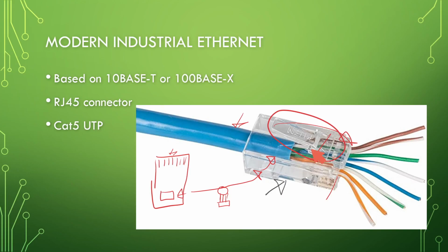The other thing that you guys might remember is when we were doing the cable testing, it was pin 1 good, 2 good, 3 good, 4 good, 5 good, 6 good, 7 good, 8 good, and then ground failed. And you guys were like, oh crap, the ground failed. Well, we have a plastic connector. We don't have a metal sheathing in our wire, so there was no way to connect that ground. As you get to different cable types, which we'll talk about in a few minutes, you will have an extra shielding there, which is grounded, so you could actually ground both ends of the connector and whatnot. But anyway, so yeah. Not very good.